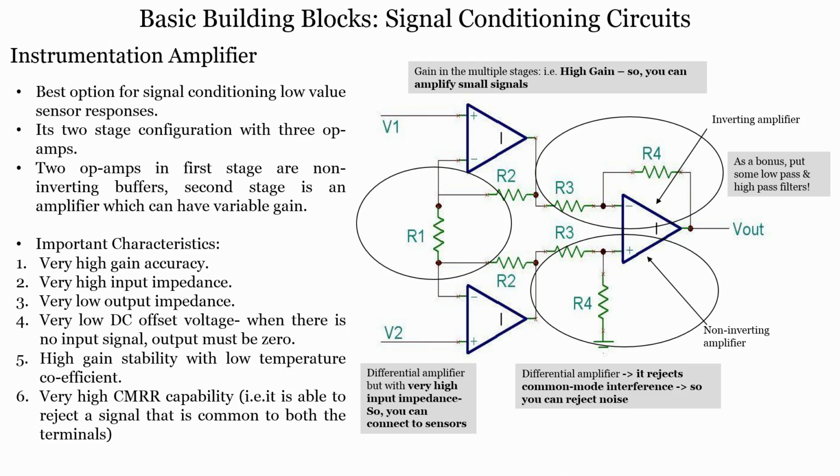Now, you know what CMRR is, right? CMRR is the common mode rejection ratio, given by the ratio of the differential gain to the common mode gain, that is, the magnitude of AD by ACM. We want ACM to be extremely low and the differential gain to be extremely high, so that we can faithfully replicate the signal and have gain only from the difference of the signals.